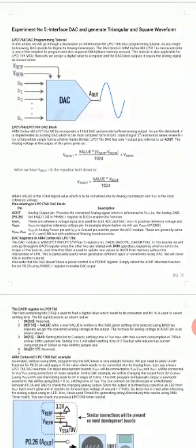Let us see how to generate this analog signal using the digital signal. You can see here a DAC block with AOUT as the output, which is producing a sinusoidal waveform, and you have B0 to Bn as the inputs, which is an n-bit input here, and there are two reference values, one negative, one positive. Usually the negative reference value we ground, so it is 0, and we give some reference positive value to the VREF-P. This is the arrangement of the DAC.